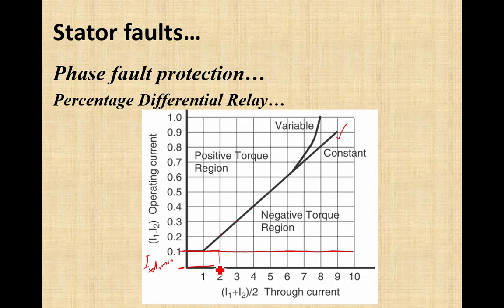will be like this. It keeps on increasing, and here it becomes like this, and this sudden rise in current is due to the CT error, higher CT error, and maybe due to slight CT saturation. Okay, it means up to this level of 8 ampere retaining coil current, the overcurrent differential was also working well, but beyond this value the difference current has crossed the pickup setting in normal condition, so the relay would trip in that situation.